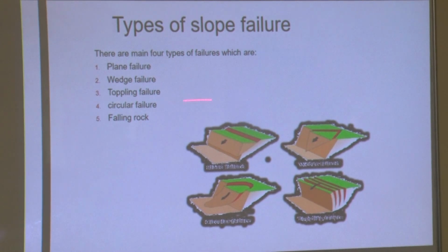Most cases in mining we face, including low depth open cut, meaning shallow depth open pit mine, and other mining accessories, overburden dam, tailings pond embankment, ash dike embankment. These are the general structures being built for different purposes. So in these cases we observe the circular failure.